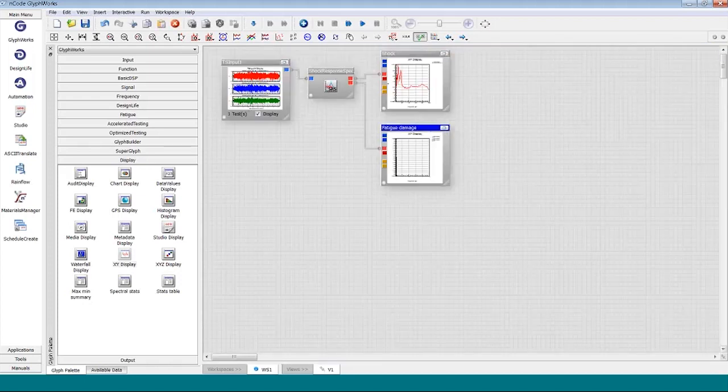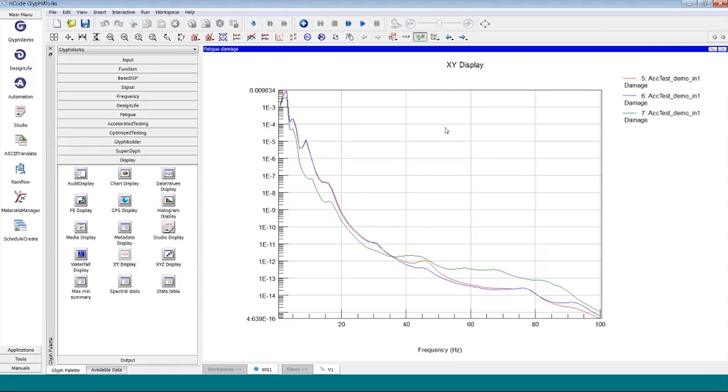That's down here. This is what we call the fatigue damage spectrum. Put this on a logarithmic plot and we can see better. We've calculated now, again for three channels, X, Y, and Z vibration separately. I'm going to look at just one at a time. As a function of frequency, now we have what's called damage. So this is our fatigue damage metric versus frequency. If you've been around durability before, you may have heard the term damage. If not, let me explain a little bit here. Fatigue damage means how much of the life is used up. We'll go back and understand an SN curve or a fatigue property set in just a minute.